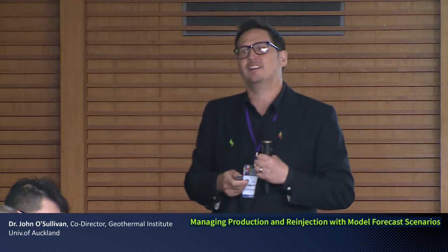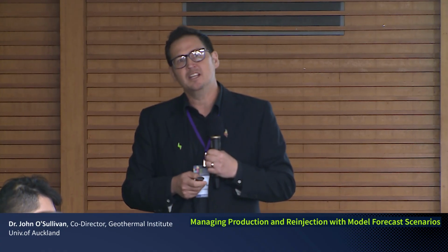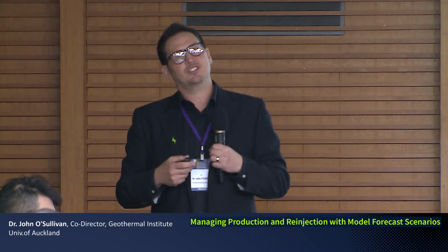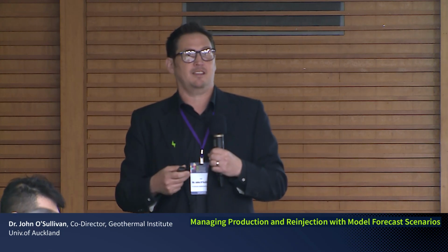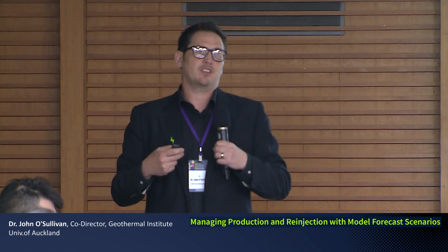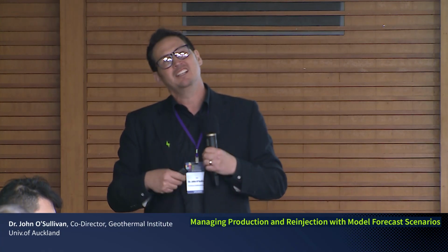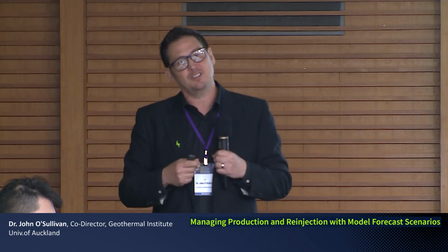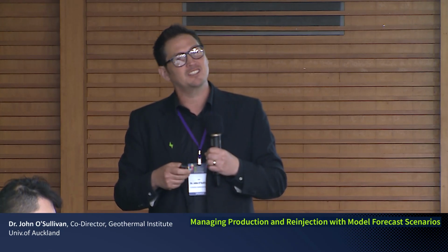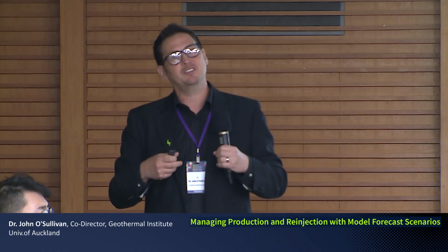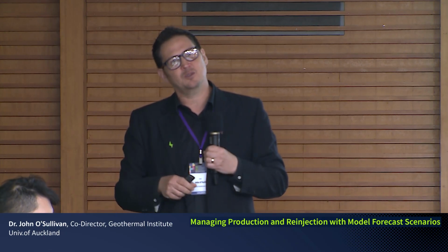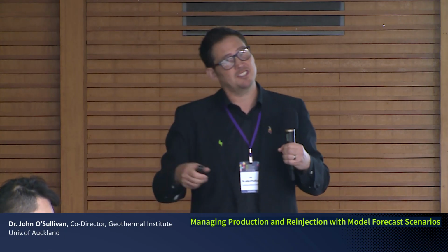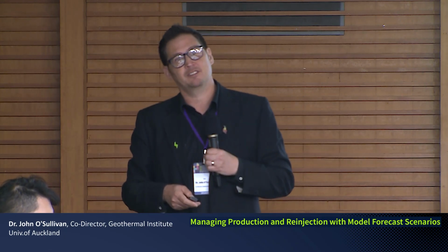In New Zealand, and potentially in Taiwan, I suspect, we have a very good managed forestry system in New Zealand, and there is a certain amount of forestry waste that is a good source of CO2 essentially, by burning wood slash or wood pellets. What we're looking at in a project which is supported by the New Zealand government in partnership with the University of Canterbury is perhaps increasing enthalpy of fluid with some boiler, extra heat from burning wood slash, capturing the CO2 and then also sequestering that as well. But any industrial processes that are producing CO2 could be used for a net negative approach.